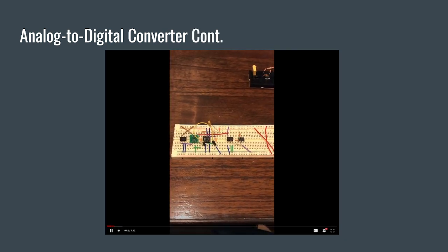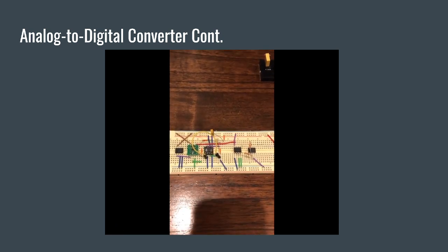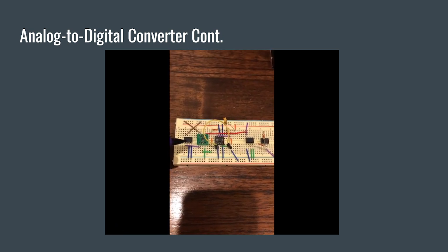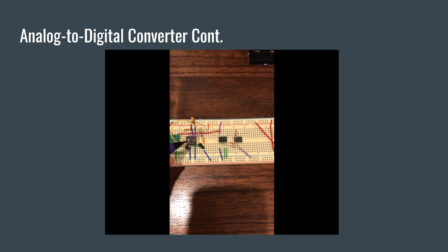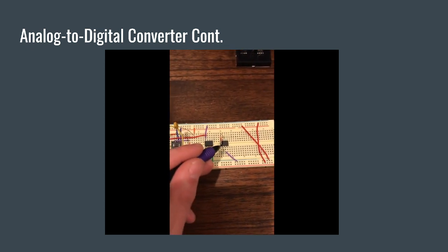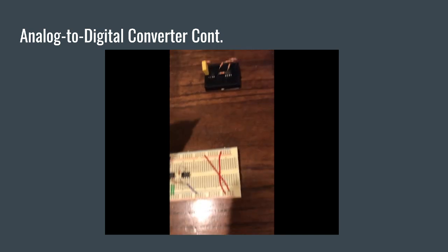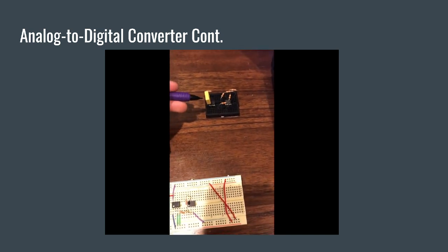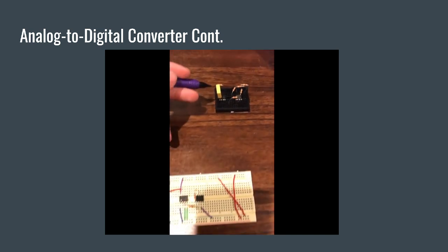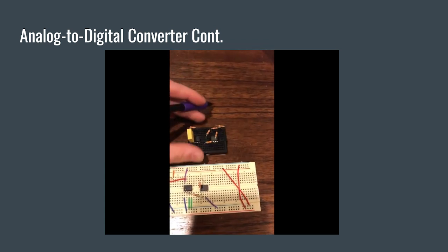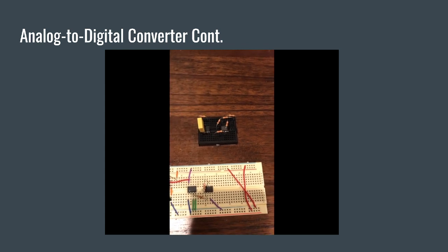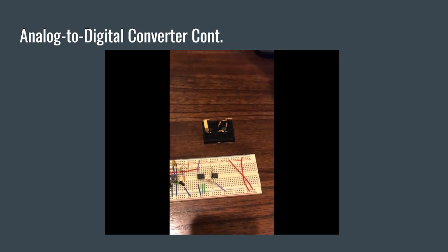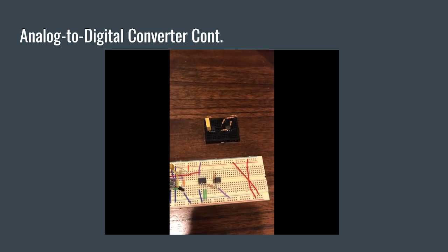This is our ADC. In our design, we are using a comparator, a D flip-flop, a crystal oscillator clock, a switch, and a unity buffer op amp, as well as this outer circuit, which we are testing because of issues with our integrator and our difference amplifier not working well in our second order filter or our first order filter.